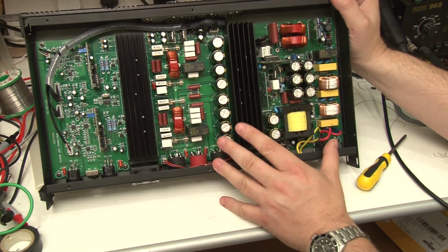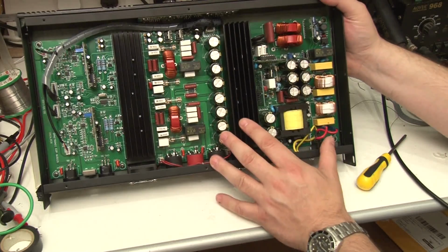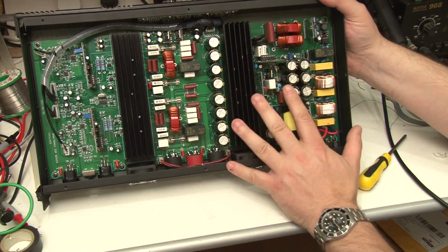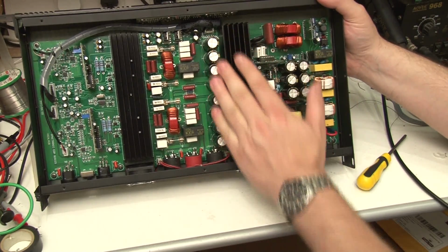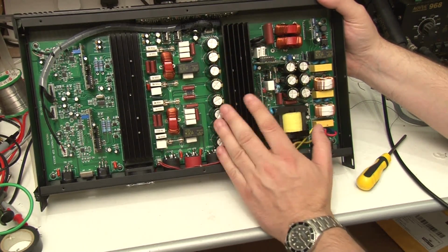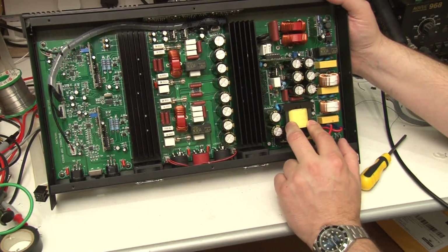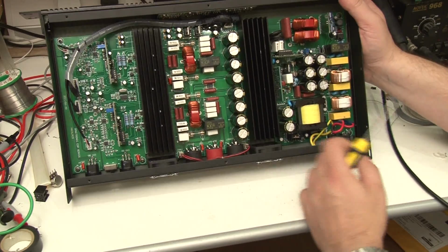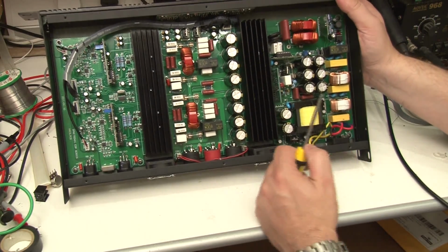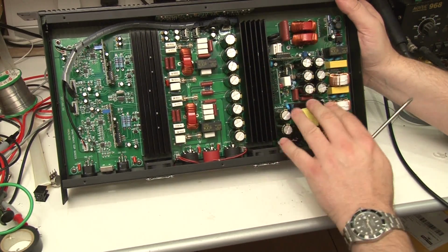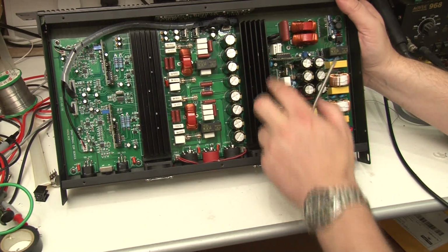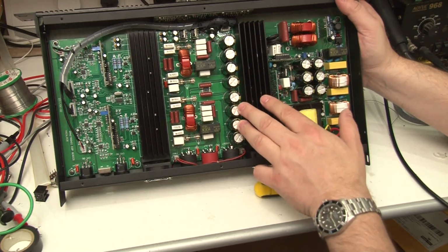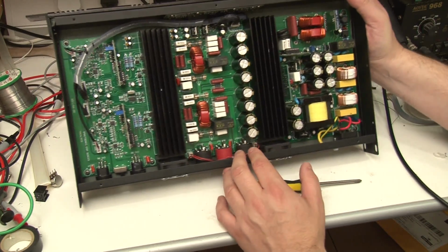And that's another advantage of Class D amplifiers: the components are much smaller, certainly capacitors are much smaller because of the higher frequency. The transformers are much smaller. It's a much more commonplace technology nowadays, where almost everything is a switch mode. So we've got a main switch mode generating a plus or minus supply, and that'll be coming onto these caps here, I'm sure. And then you've got